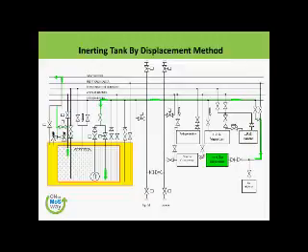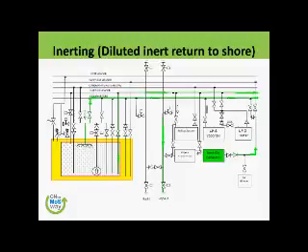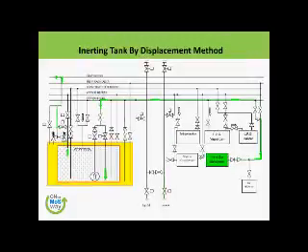It is worth mentioning because our next exercise is going to be on the membrane tank, a few of them. Ventilation header, inert gas header, condensate return line, vapor header return line, liquid return line, etc. So that is the way we were doing it. We are displacing from the bottom line and taking the lighter stuff out from the top.